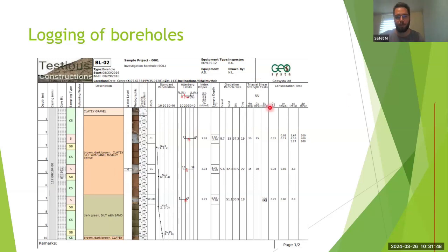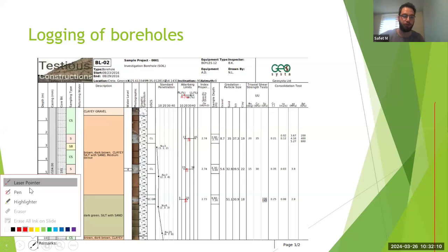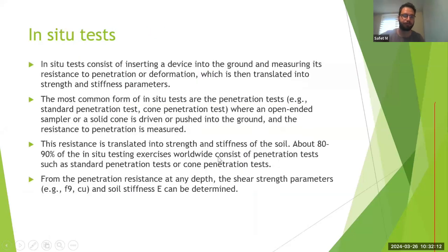We're also going to put there the name of your project and the name of your borehole, because you're going to have different names for the boreholes on the site. One really important one is the location in coordinates, because you're going to come back to that borehole and use it eventually in the future. So it's really important to have it in your database with the coordinates.